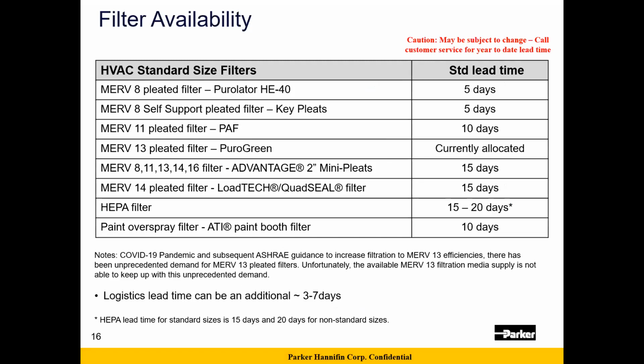As far as filter availability, that's a big situation today because there's a big run today on a lot of customers wanting high efficiency filters in order to open up their businesses, because in many states and jurisdictions, they are requiring a minimum filter efficiency level and higher. Some of them are saying you must meet MERV 13 and higher. So it is putting a fairly substantial run on filters of that type.